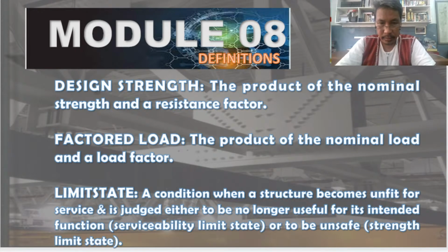Okay. So next definition, what is limit state? It is a condition when a structure becomes unfit for service and is judged either to be no longer useful for its desired or designed function. That is serviceability limit, because there is a sense of performance to it.